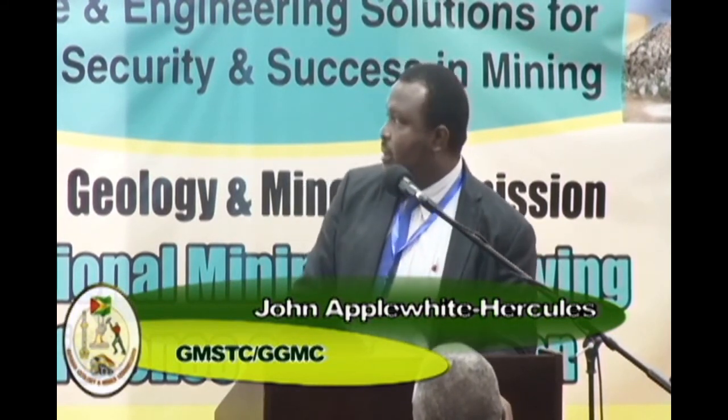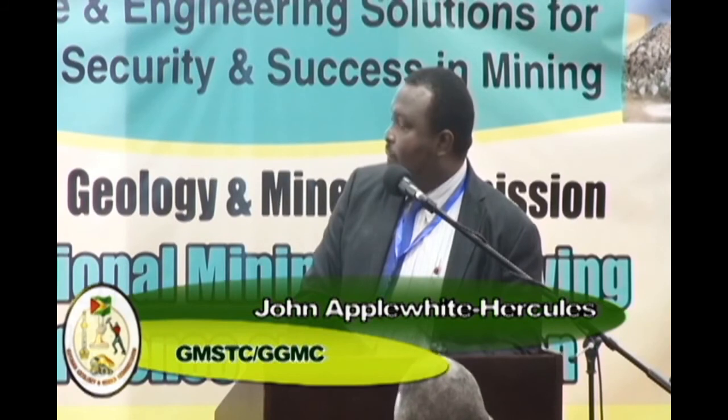What's the depth of investigation of your tool? Okay, so the model was able to go to a maximum of 500 meters into the ground. But of course, the software can give you results up to 1.5 kilometers. However, after you would have passed, let's say, about 700 to 800 meters into the model, the accuracy of the transformation decreases. So good data can safely be gotten for 500 meters, and that is why my model was set at 500 meters depth.